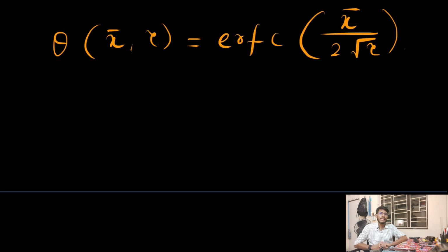There is also another thing: if you can put an oscillating temperature as a boundary condition, that for any time t greater than 0, my T is equal to some T1 into sine omega t. So that is some oscillating temperature. For that also an exact solution exists, okay, but the approach is a bit different.